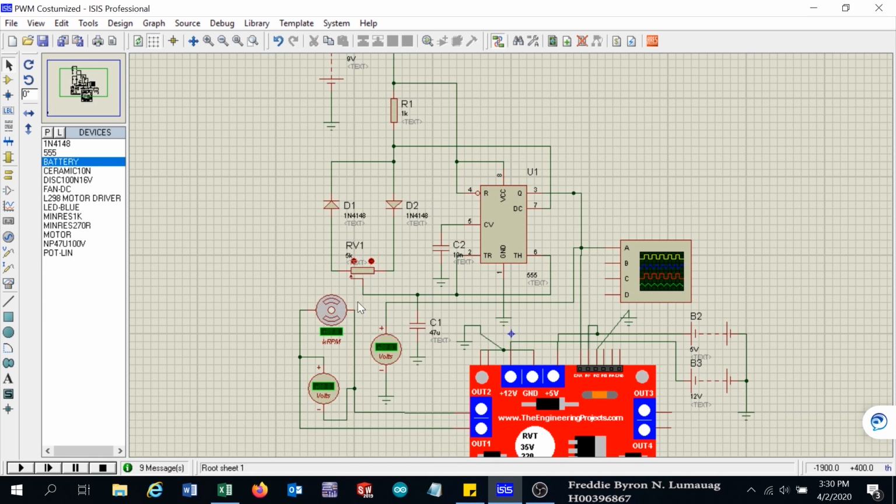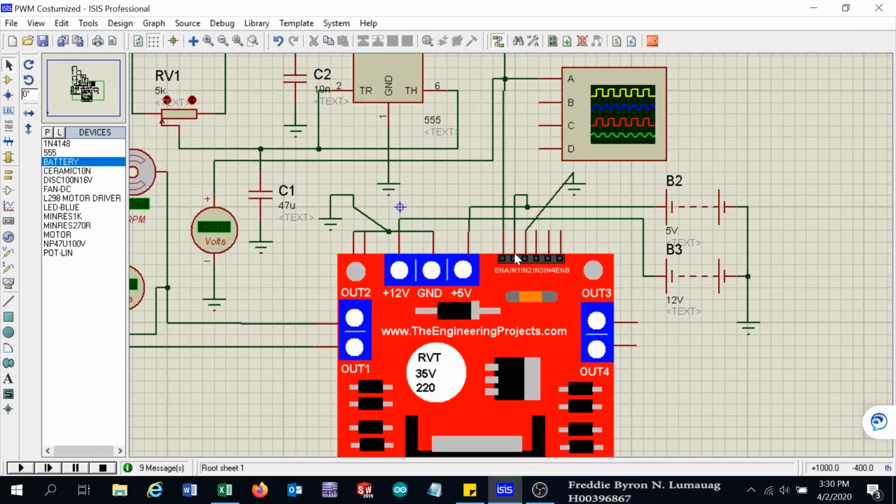It is suitable to control the speed of the motor. Of course, we can use a microcontroller to supply the PWM, but here we want to use a source different from a microcontroller, and it still works as long as you have the PWM signal fed to enable A. In the same way, you can use a second motor connected here.